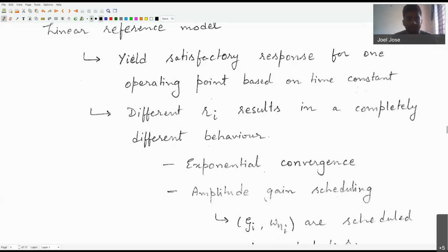Correct. So we will be changing the values of the gains of the filter. We'll be tuning the filter slightly differently when we receive higher amounts of the reference signal, and we'll be tuning the values differently for lower amounts of the reference signal. So that in both cases, more or less, the velocity constraints and the saturation constraints are matched.